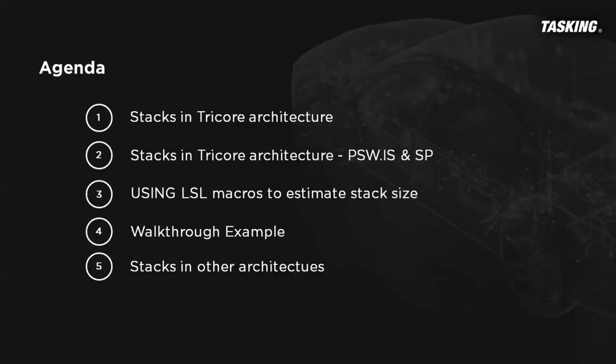In this example, I'm going to build a very small yet effective multi-core based application, and I will measure the stack sizes that I used for my application. And after that, because the TriCore architecture is quite complex, it has different controllers or standby controllers, and we are going to see how the stacks in these architectures look.